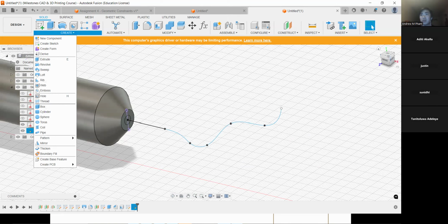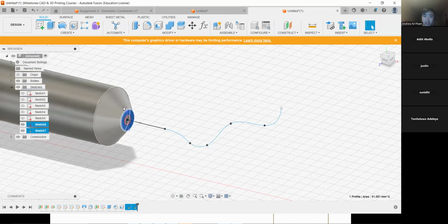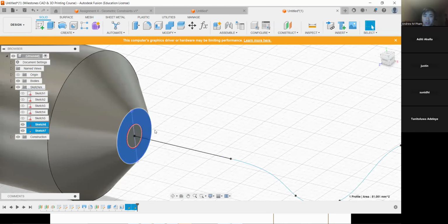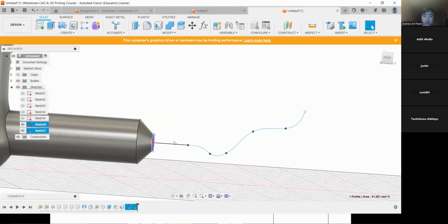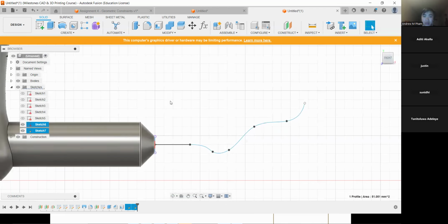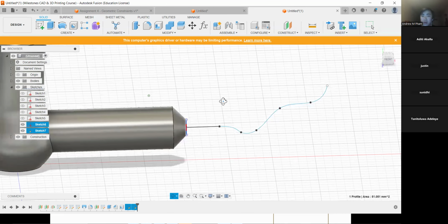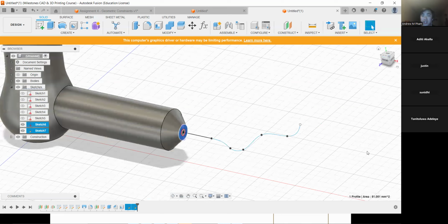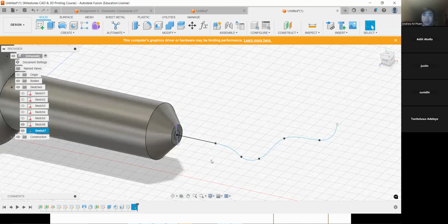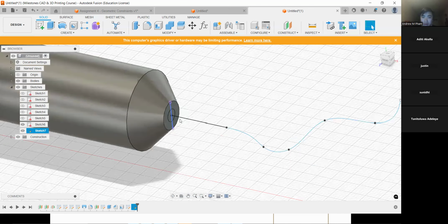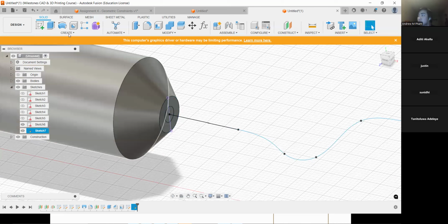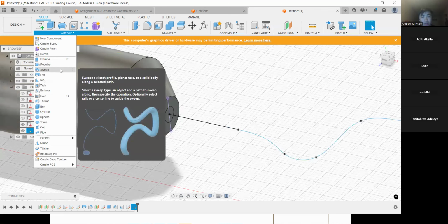When I project the circle, I'm getting a purple circle instead of a line. Okay, that's likely because you're drawing a sketch on the wrong plane. If you draw a sketch on this highlighted region, then when you project the circle, it'll be a circle. But because I'm drawing a sketch on the front plane, from this view the circle from this perspective is actually a line. So I would check the plane that you're sketching on, if that makes sense. Anyways, to create our sweep, sorry, I'm going to go under create.